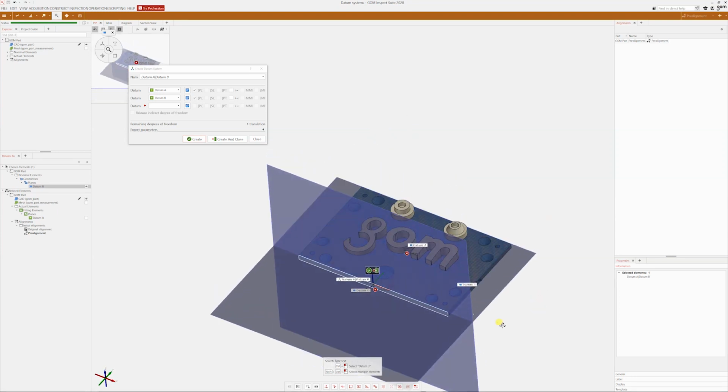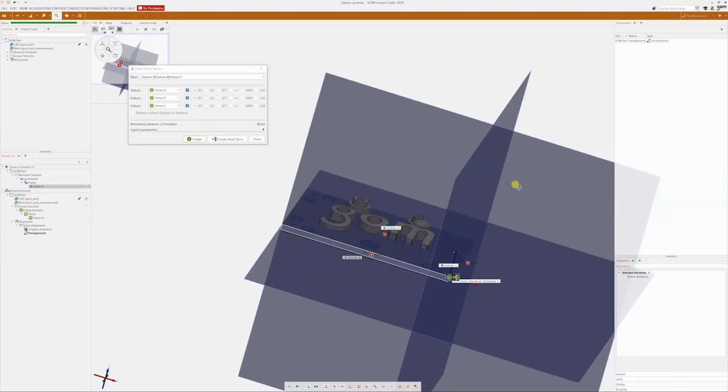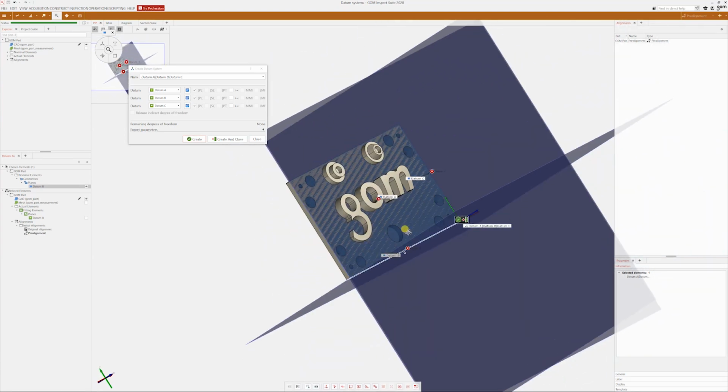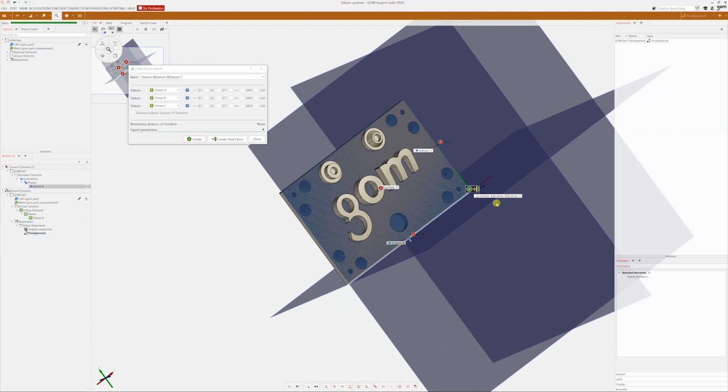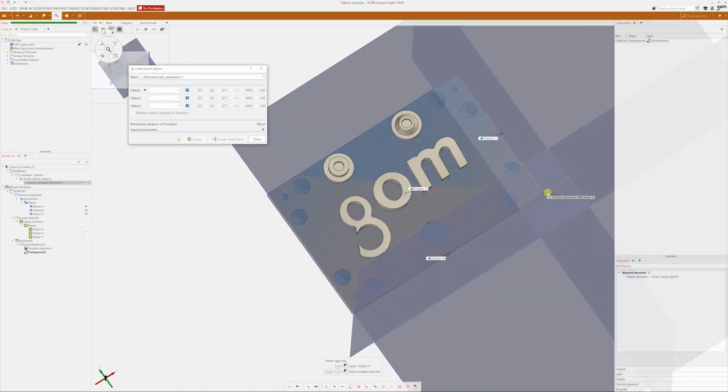And the only thing that remains is the translation on the x-axis, which will be taken by datum C. And now we have three perpendicular planes intersected by each other, and here we have the origin. Good. So let's see also an example of taking the degrees of freedom from the part.